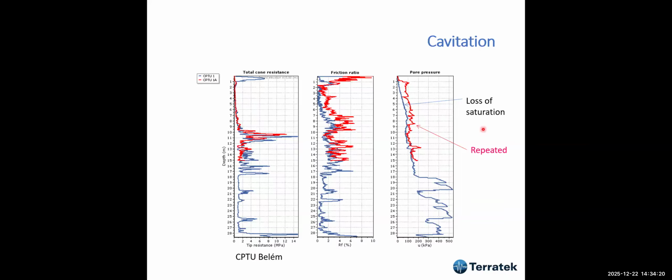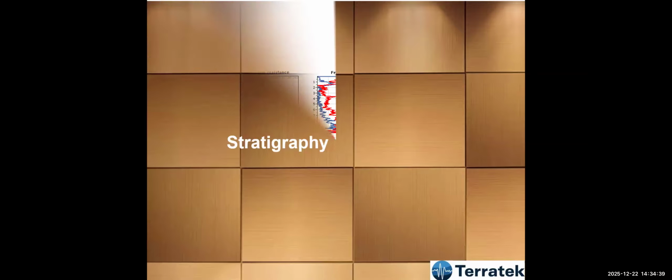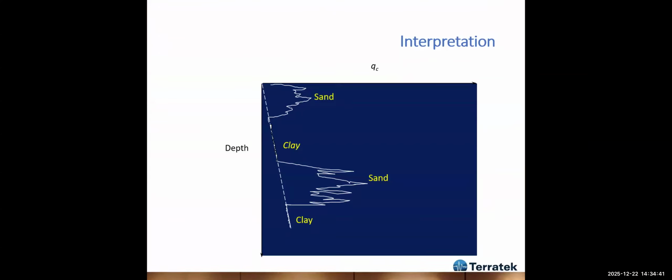Sometimes we have to do that, and that's why we always have to look at the data before the drill rig or the CPT rig leaves the site, in order to ask or not to carry out another test for some reason. Okay, and stratigraphy.